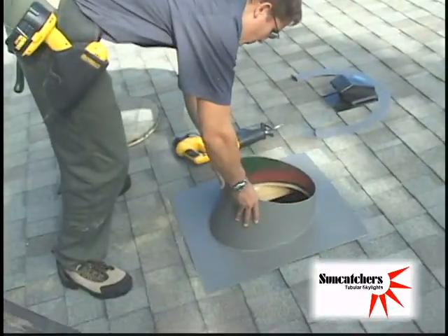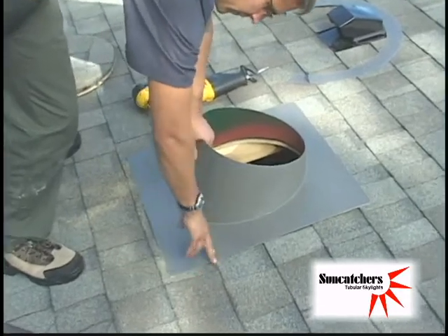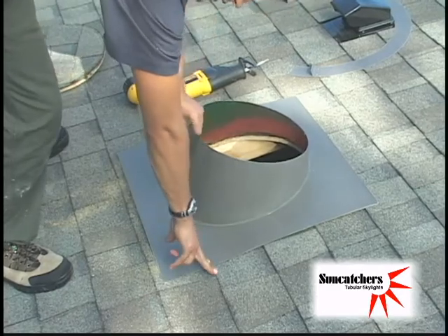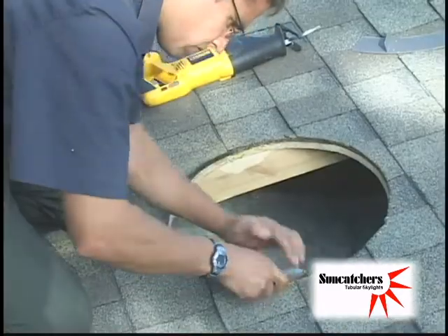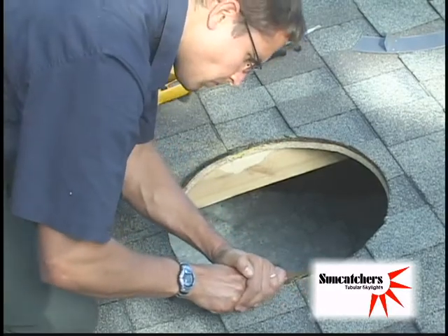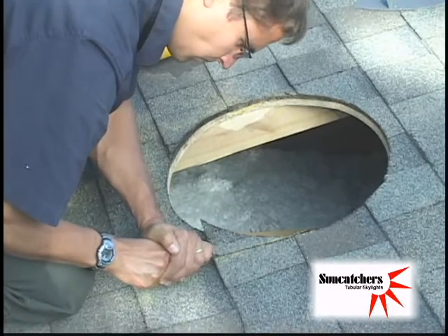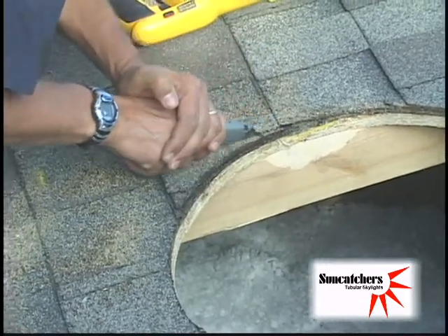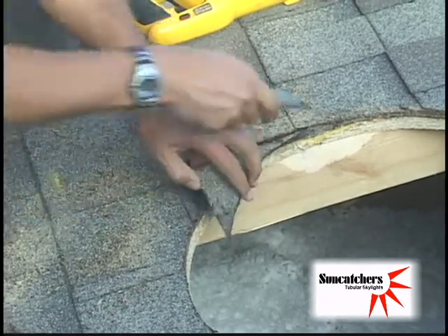To establish which course of shingles to put the flashing under, the general rule is 1/2 to 3/4 of the flashing should be under the shingles. Make a straight line and cut off excess shingle with a hook blade, ensuring to cut the top layer of shingles only and not the one underneath. At this time, you may also need to cut away any of the shingle portion that overlaps the truss.